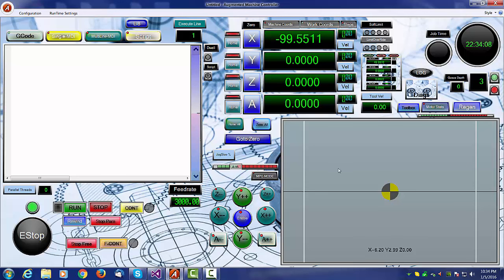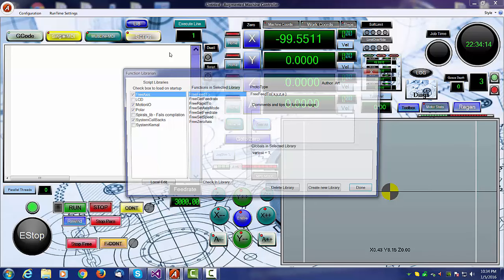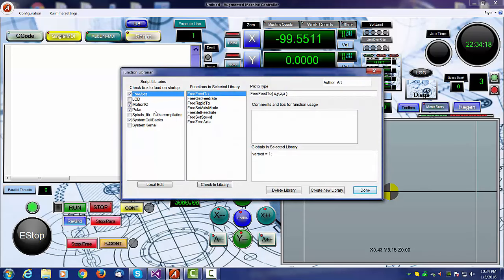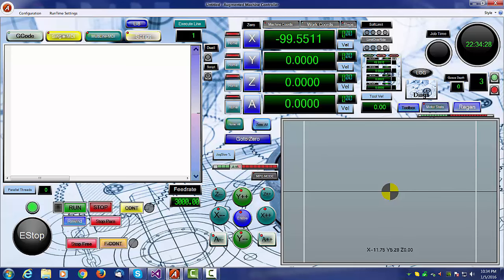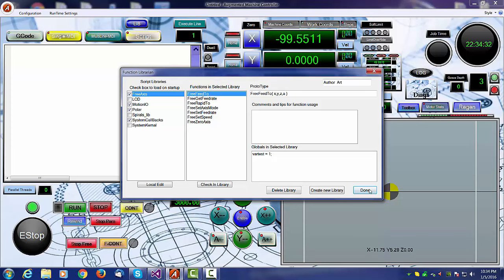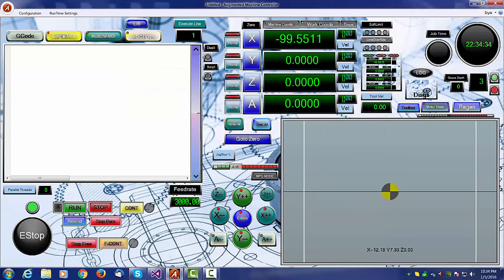However, in our case, it works fairly well, because you design your screen scripts in one section, which is the final section loaded, and your library scripts load about second or third in order, so all the other scripts in the system can take advantage of any library script. Okay, that's the first thing that you need to understand, and that's why you don't want to put any scripts into a library that talk to screen objects. You can create global variables inside a library, and then in your screen scripts you could talk to those global variables. That should work fine.